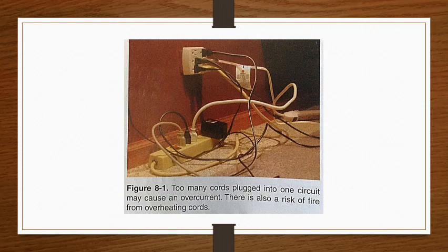All electrical circuits must have an overcurrent protection device installed. An overcurrent protection device, or OCPD, shuts off power to a circuit when the current in that circuit exceeds the ampacity rating of the OCPD.